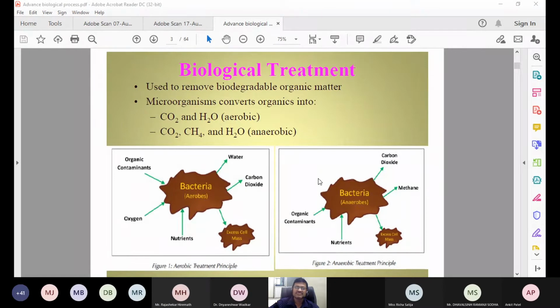Why? Because in the first bottle from 8 it becomes 5. In the second bottle from 8 the oxygen level becomes 3. It means the bacteria has done more consumption in the second bottle. It means indirectly that there is more organic matter in the second bottle.